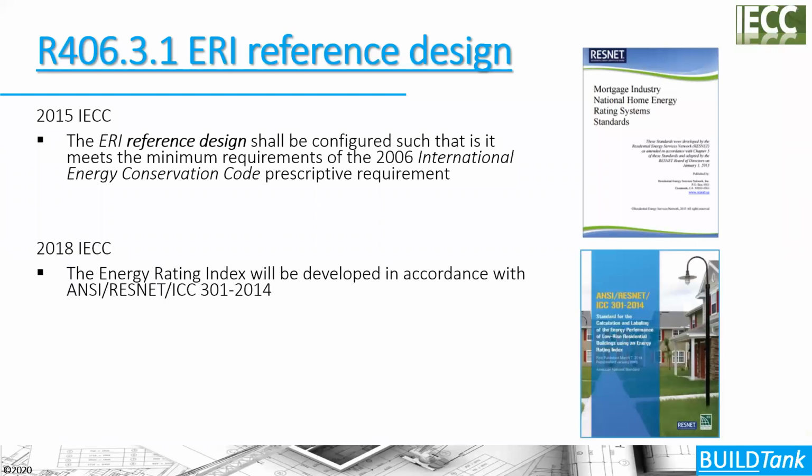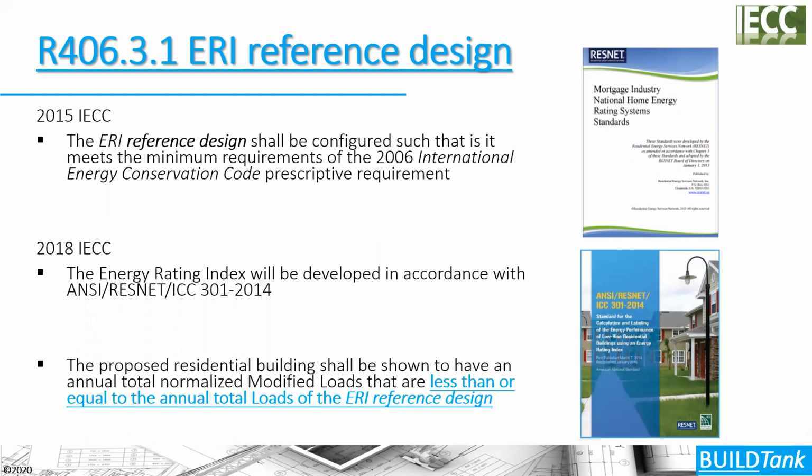Now, by the time the 2018 IECC was developed, this non-proprietary ANSI standard was created that describes how to develop an energy rating index score. It happens to be the same standard that ResNet uses to develop the HERS index score, but the ERI score, we'll see here, has been amended when it was adopted into the 2018 and 2015 IECC. So the scores aren't the same number actually for the code ERI and the HERS ERI, or the ResNet HERS ERI.